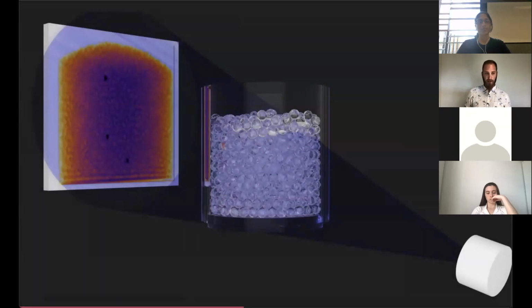So what Mara did is we took our X-ray system. Here in the bottom right, we have an X-ray source. It's like a light bulb, and it's light shining out, blue light here, which are the X-rays. And then they get caught on a detector panel in the top left. And that detector panel is like the camera. And we can see everything between the source and that detector panel. And so we're seeing here a projection of all of the grains onto that detector panel.